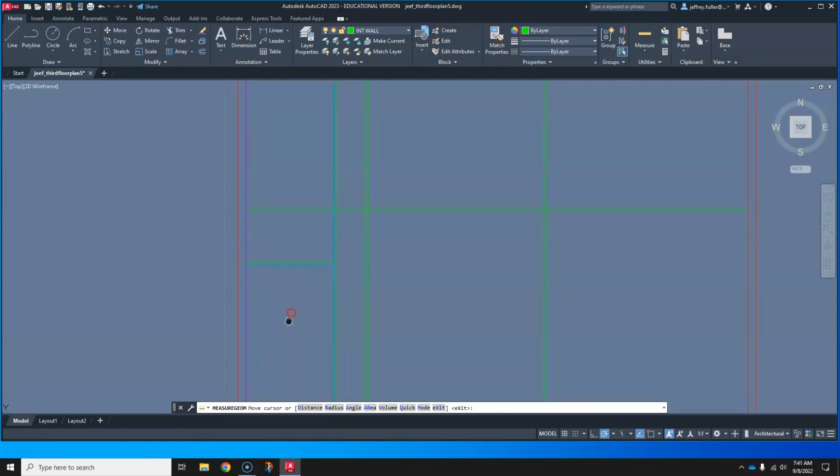All right, so we have to figure out what we're going to do with all of this space, and sometimes it takes a little thinking. All right, so what I want to do first is I want to create a line. I'm going to start down here at the corner, and I'm just hovering over that corner to turn on the reference point. I'm not clicking on it, I'm just hovering on it. So hover on it, I just turned it off by hovering over it a second time. Hover over it again, and I'm turning it on, and you can see that I've got that guideline following the cursor, that green dashed guideline, if you can see that in this video.